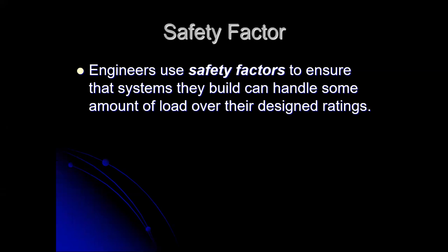It reduces the areas that we're working with, and so it buys us some leeway for them to be damaged or corroded and still be able to handle the loads that we rate them for. So safety factors all around are a good thing, and all else being equal, we'd want the safety factors to be as high as possible.